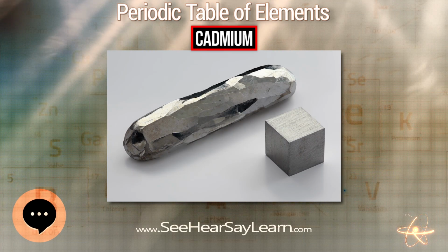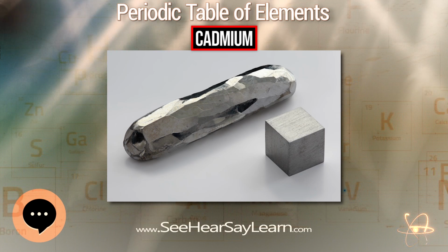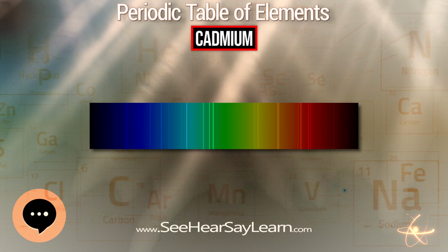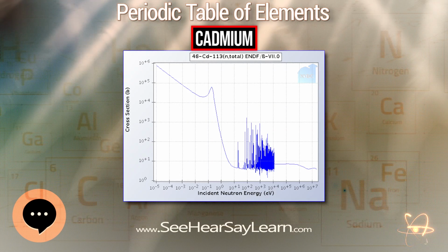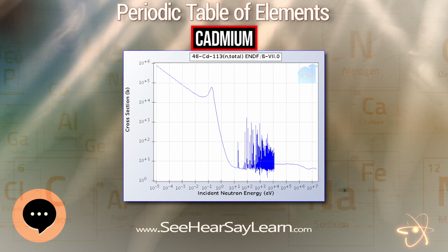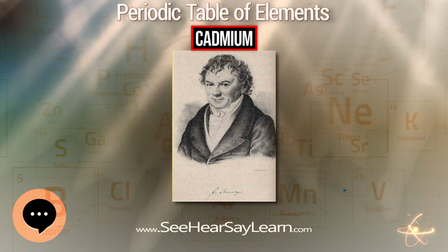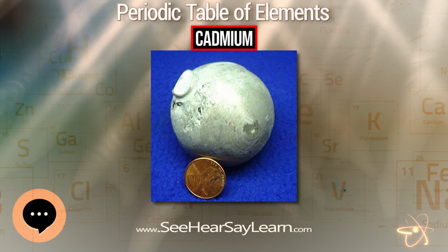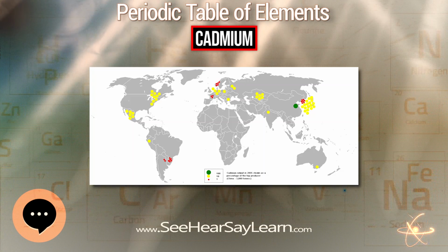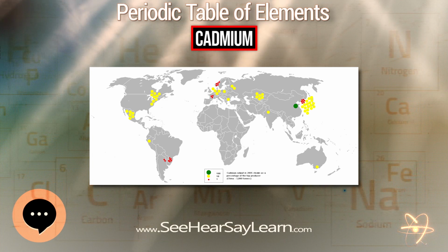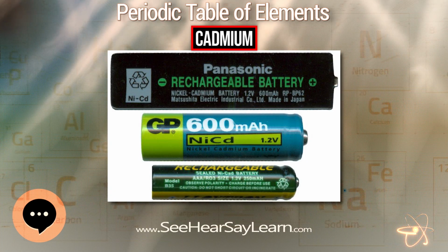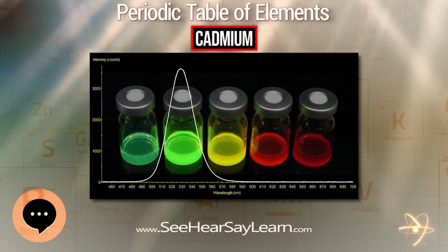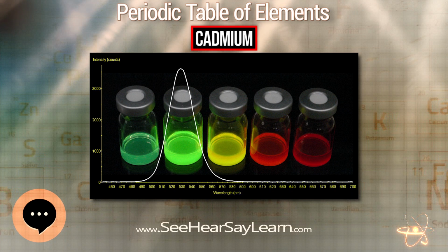In 2009, 86% of cadmium was used in batteries, predominantly in rechargeable nickel-cadmium batteries. Nickel-cadmium cells have a nominal cell potential of 1.2 V. The cell consists of a positive nickel hydroxide electrode and a negative cadmium electrode plate separated by an alkaline electrolyte. The European Union put a limit on cadmium in electronics in 2004 of 0.01%, with some exceptions, and reduced the limit on cadmium content to 0.002%. Another type of battery based on cadmium is the silver-cadmium battery.